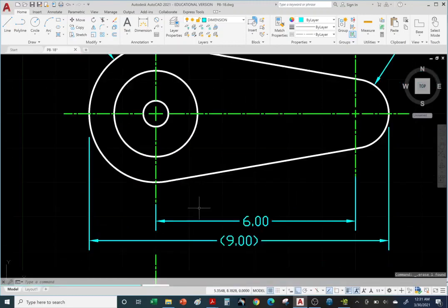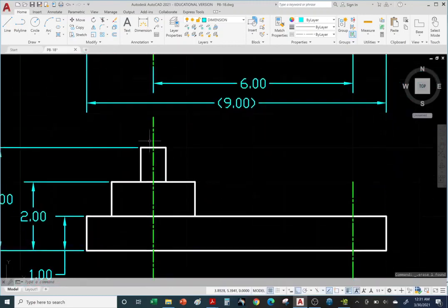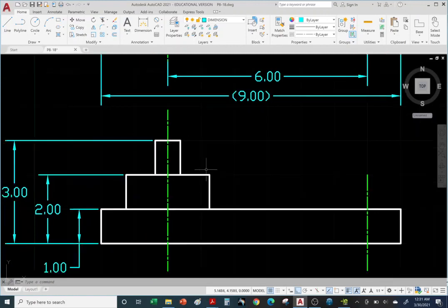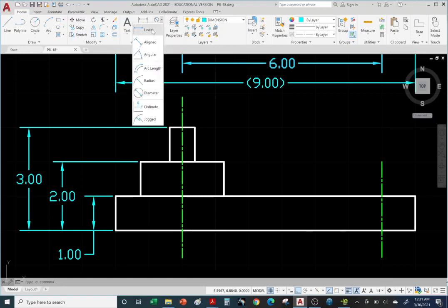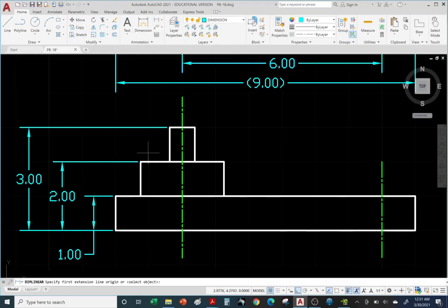Instead, you have to dimension the rectangular view. So these are round shafts, but from this perspective, it looks rectangular. So you actually have to dimension these with the diameter, because these are solid shafts and not circular holes. Okay, so we need to throw in linear dimensions. Okay, so we're going to go from, let me turn on object snap, from this point to this one.